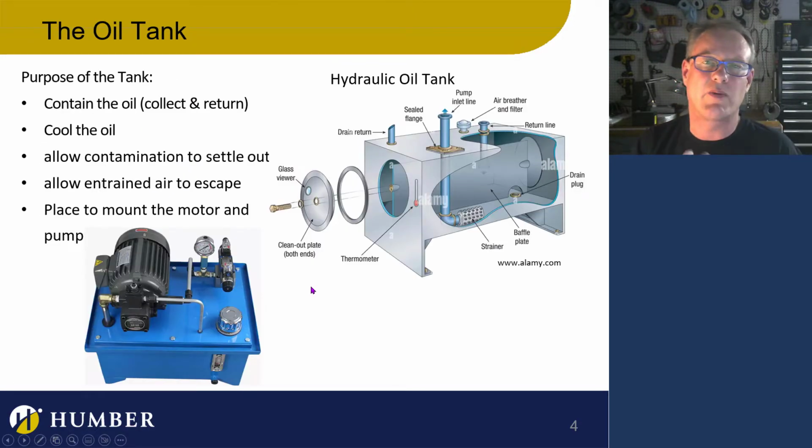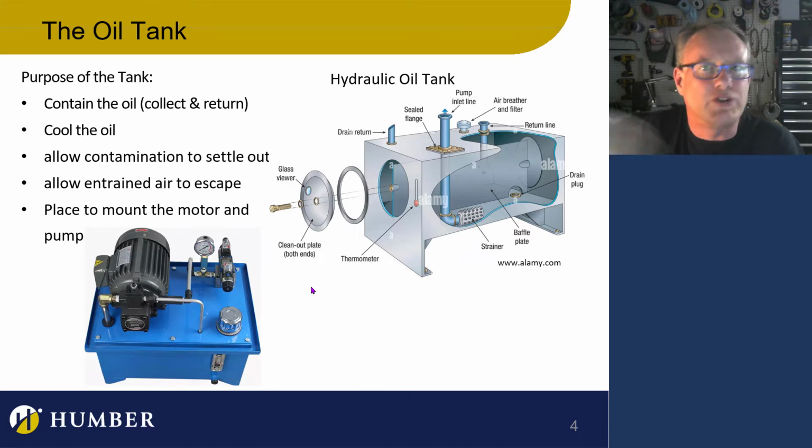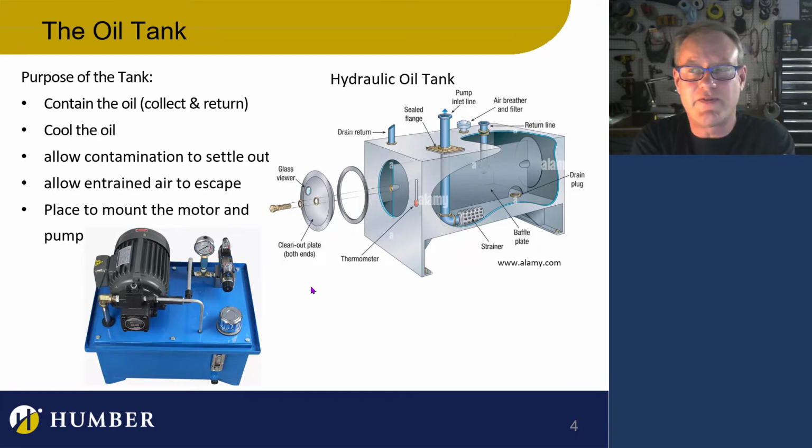So let's start with talking about the tank and move on to all of those other things we looked at. So the tank. What does the tank do? It holds the oil. It's also a place for the oil to return. It's different from pneumatic systems, as we remember from pneumatics. The tank is the atmosphere. In this case, the tank is a place for us to recycle the fluid too. We do a lot more than just hold the fluid in there. We recycle the fluid, we put it in there, we clean it, we condition it, and we cool it. In some cases, we actually heat it.